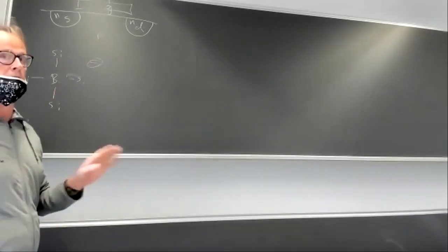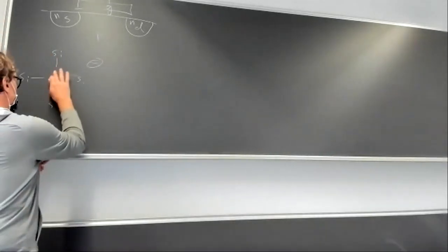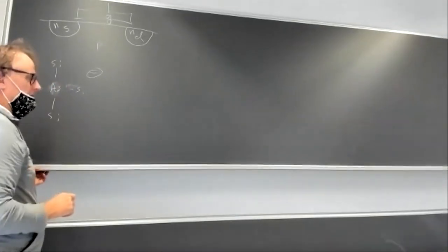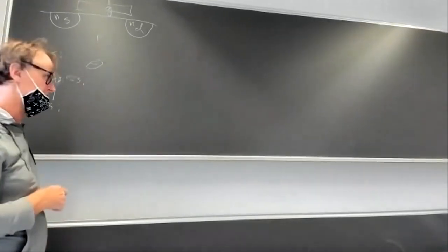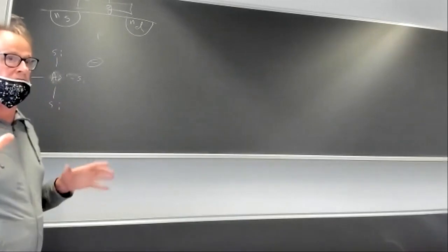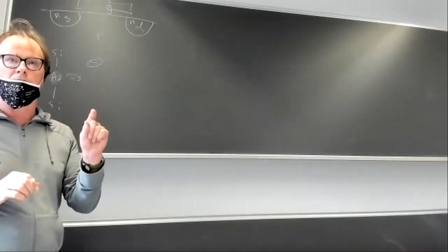It's easily broken loose. I think it's actually arsenic. Phosphorus or arsenic contributes an electron. I think it's phosphorus. Yeah, phosphorus, it has 1 extra electron in the outermost shell. The binding energy of that extra electron is very small. It's only about two thermal voltages.